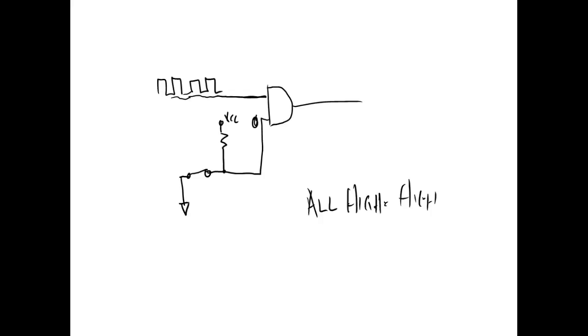So if you said all 0s, that's great. That's what it is. Because it says it takes all highs to get a high. And there's no way in the world I can get all highs if I got one of my inputs connected to 0. But when we come over here and we open this up, now it allows us to get a what right there? A 1. So now every time the input goes high, we have all highs. The output would go high.